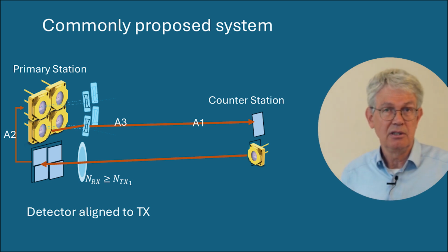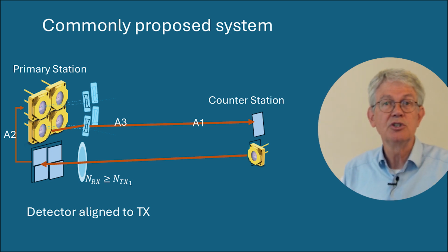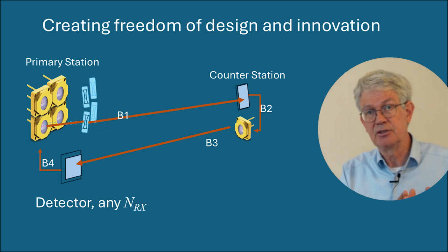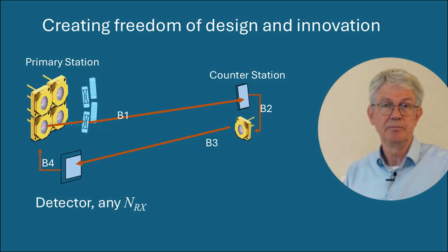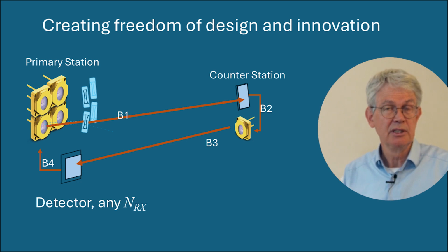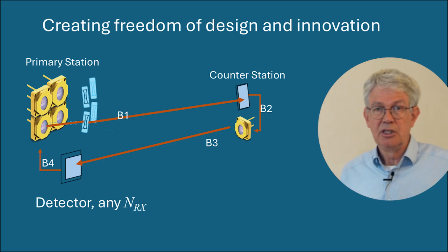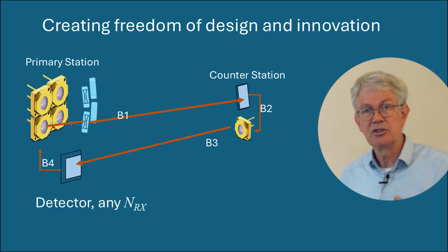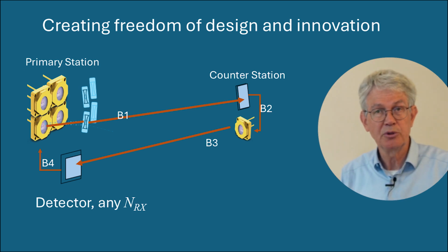And a topic that I'm debating in detail in the paper is how can we solve that? How can we decouple the number of segments of sectors at the transmitter from the number of segments at the receiver? And there is a way of doing that. But we need a little bit of help from the counter station. The precise detail with using codes in different sectors and how to detect that in a very efficient way, using only very small amounts of signal processing power.